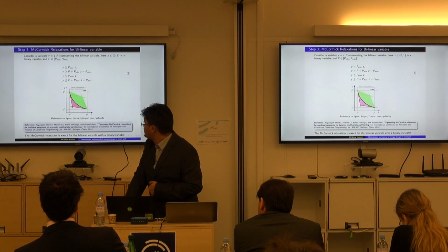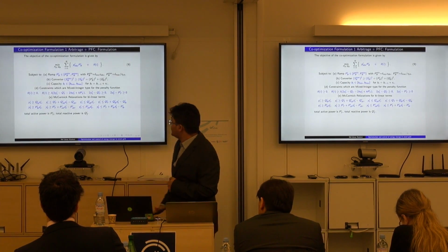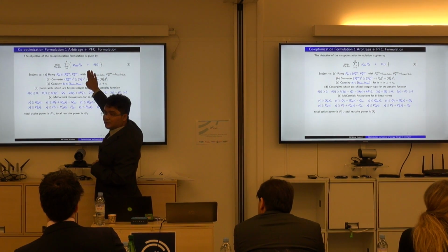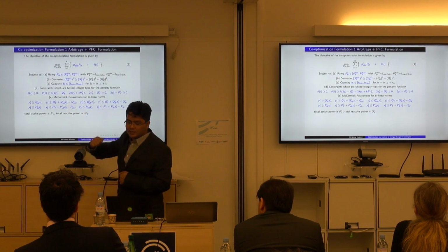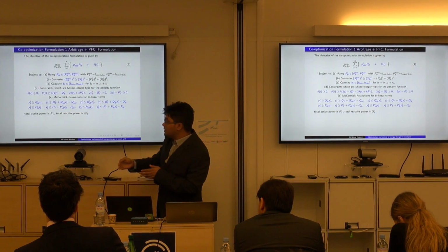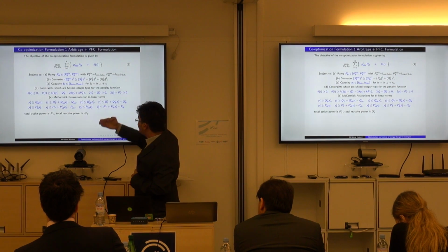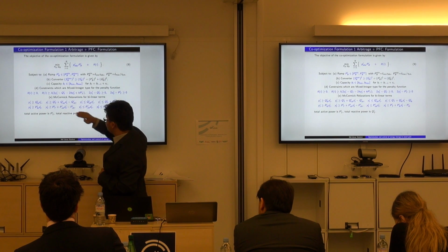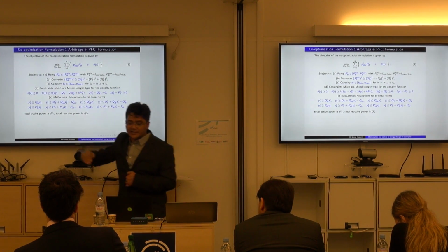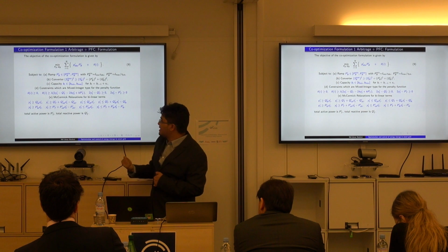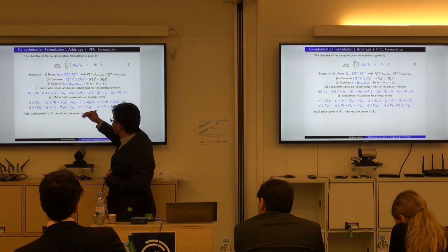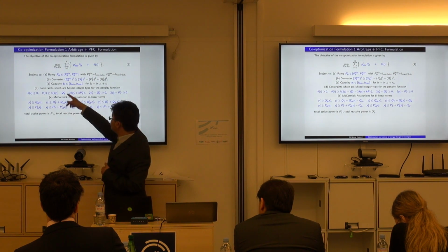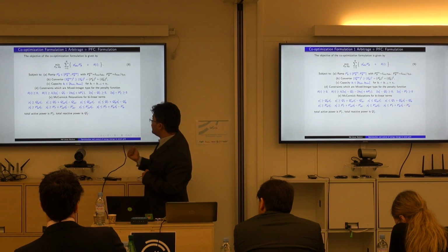Now merging all the constraints, our cost function has the arbitrage component, and we denote theta as the penalty function, which penalizes my power factor violation. I'll go through the set of constraints without going into detail. First is the ramp constraint, which is how fast the battery can charge or discharge. Then there is the converter size, which is how much apparent power the converter can supply. Then there is the capacity of the battery, which is also evolving over time.